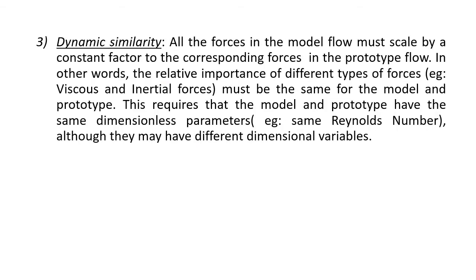And the last similarity is dynamic similarity. All the forces in the model flow must scale by a constant factor to the corresponding forces in the prototype flow. In other words, the relative importance of different types of forces, for example viscous and inertial forces, must be the same for model and prototype. This requires that model and prototype have the same dimensionless parameters like Reynolds number, although they may have different dimensional variables.